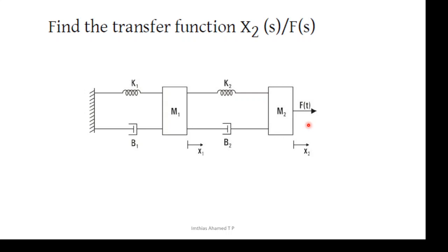f(t). So I hope you recall there are 4 steps. Step 1 is identify the input and output. Step 2, write the differential equations for the system. Step 3, take Laplace transform. Step 4, rearrange terms. Let us do it.